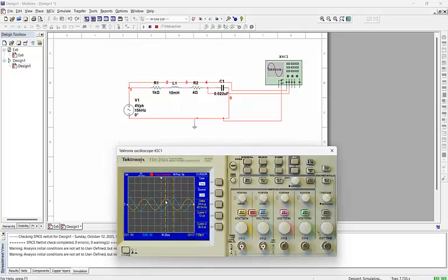One is the first cursor for the first peak and the second cursor for the second peak, and we are interested in getting the delta between them. So delta here is 24.4 microsecond. You have to enlarge properly, the second pair division, and manipulate it to the exact peak in order to get an accurate result. So here the delta is 21.2 microsecond.